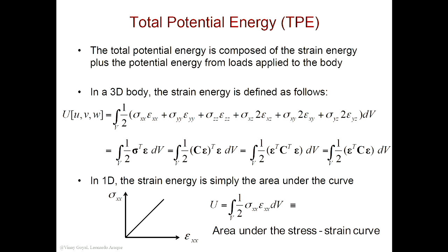Okay. And then we know that stress is related to strain through the constitutive relationship. So stress equals the constitutive relationship, Hooke's law, basically C times epsilon. So the stiffness matrix times the strain. And I gave you the formulas for C two weeks ago. If I apply the transpose to this equation, it basically flips the order. Now remember that the stiffness matrix is symmetric. Remember that? So therefore, C transpose is C.